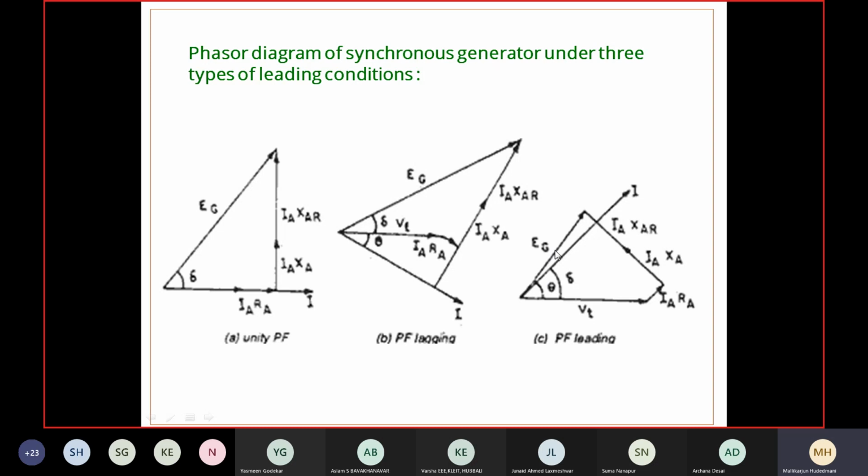What is exactly observed here is that when the system is highly leading, with a very superior power factor, the terminal voltage maintained at the synchronous generator to deliver that megawatt is very nominal, and it serves very effectively and easily. When the same synchronous generator is working at a very lagging power factor, you can see the magnitude of the generated voltage is very dominant here. It has to overcome all these drops and oppositions inside. Hence it is like this.